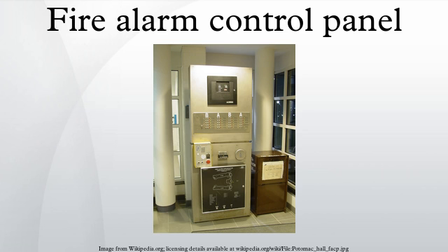Alarm, also known as fire, or general alarm. This indicator is lit when an alarm condition exists in the system, initiated by smoke detectors, heat detectors, sprinkler flow switches, manual pull stations, manual call points, or otherwise. Along with the indicator on the panel, notification appliances, such as horns and strobes, are also activated, signaling a need to evacuate to building occupants. In an alarm condition, the fire alarm panel indicates where the alarm originated.